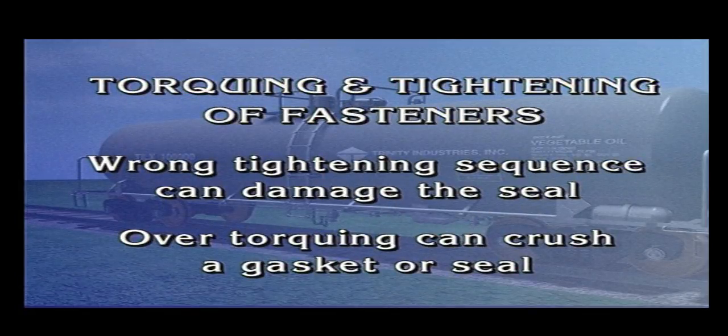Another important item is the tightening sequence and torquing of fasteners. Improper torquing of the fasteners or tightening them in the wrong sequence could prevent the gasket or seal from doing its job.